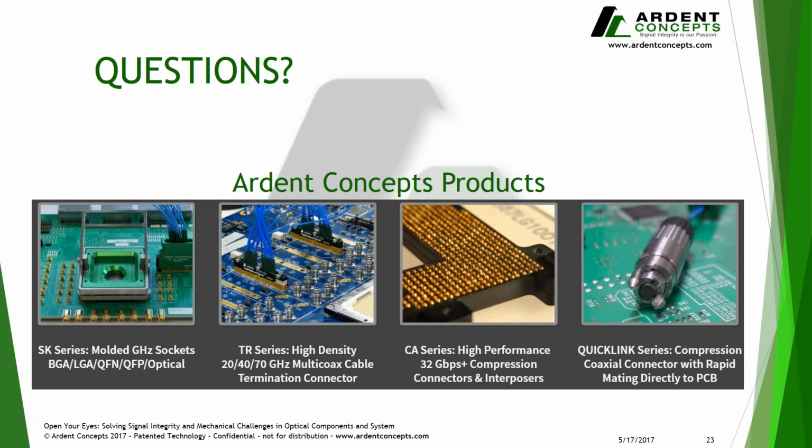So as I mentioned, that's the TR block assembly, and we included 6 inches of cable plus a 1.85 millimeter connector. So what we were able to do was, using another TR device, design a special test fixture that could bolt right to the end of a current TR device, and we can de-embed right up to the reference plane on the compliance pin of the TR. Then using a port extension, we moved the reference plane to the 1.85 millimeter connector of that measurement TR, and thus we were able to obtain those through measurements from the 1.85 millimeter connector to the TR interface.